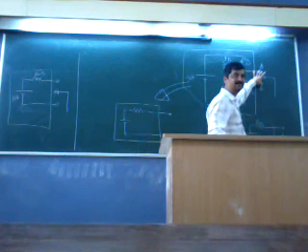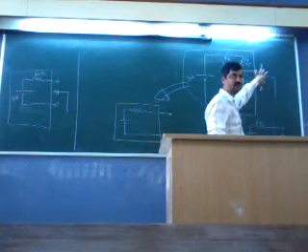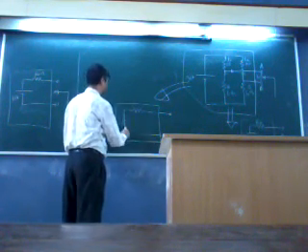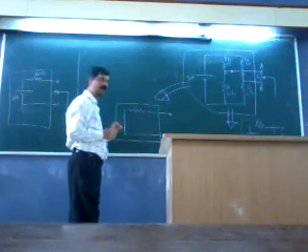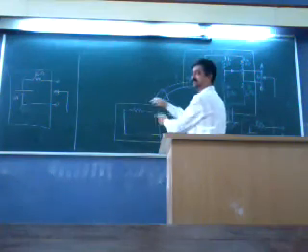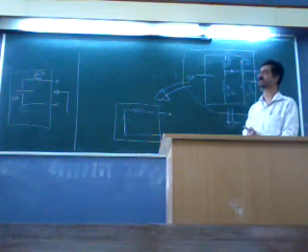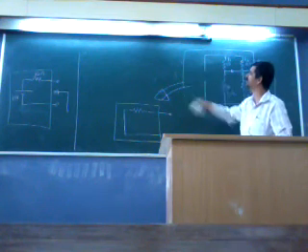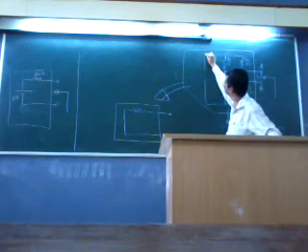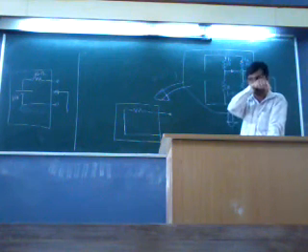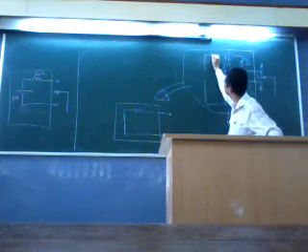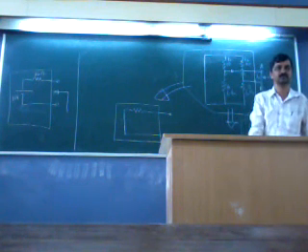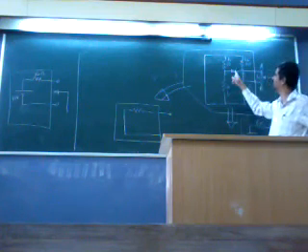This must be 0. This must be 0. So when this is 0, you should look only at the resistor. So when you make the voltage source 0, what happens? Voltage 0 means these two are same. So when you go on reducing the voltage source, a voltage source sourcing 0 volts is a short. Then you find the equivalent resistance.